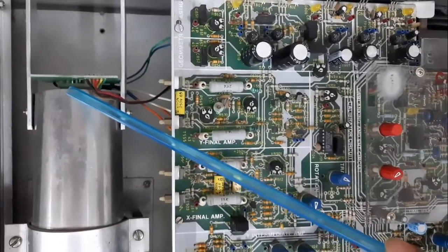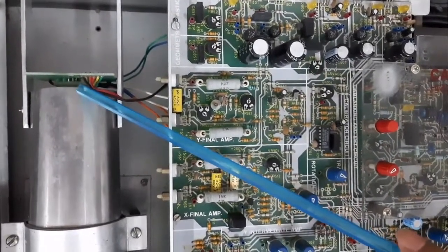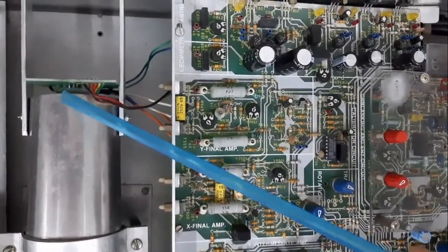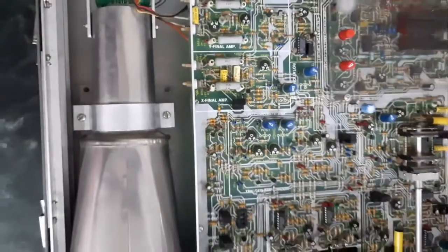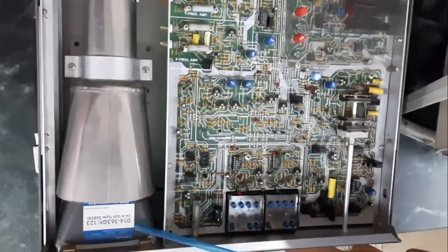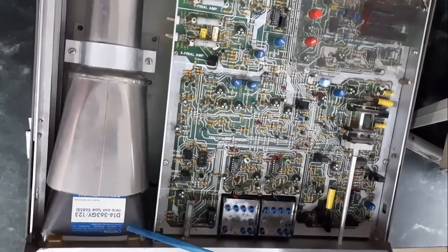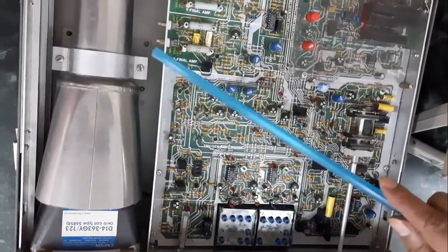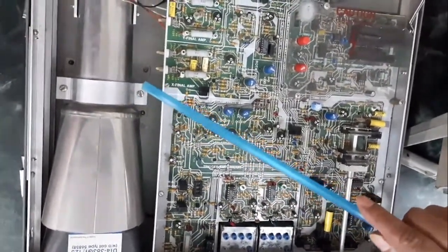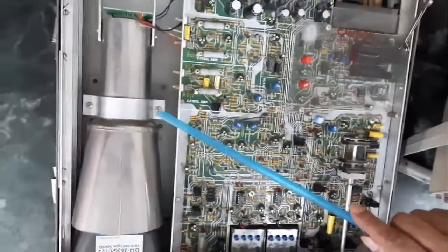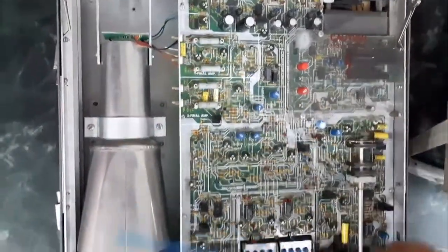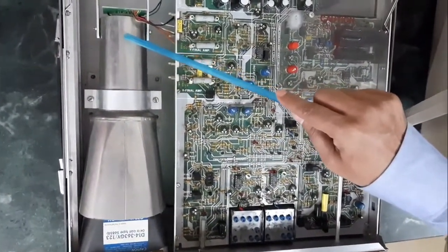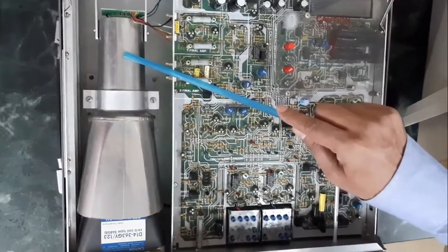So that is the given part of the CRT, and we have already seen it in our theory class. So I think there must be no doubt about this part, what is available inside the CRT. But still, I have to disclose those things again. Inside the CRT, you have the electron gun assembly, definitely the cathode, which is indirectly heated, as well as the grid with a 0.25 mm aperture, the hole that makes the narrow beam of electrons. So that is available in this whole section. After the cathode and the grid, we have the vertical side of the plates and the horizontal side of the plates.